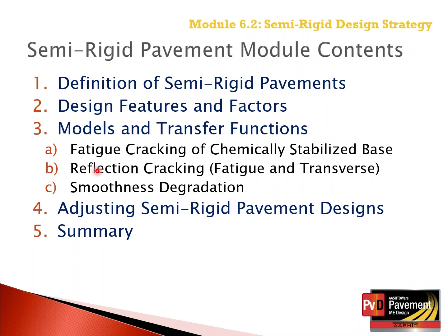So only three: fatigue cracking of the chemically stabilized layer, reflection cracking, fatigue and transverse, and smoothness degradation. These are the only three distress variables that will be discussed within this model on semi-rigid pavements.